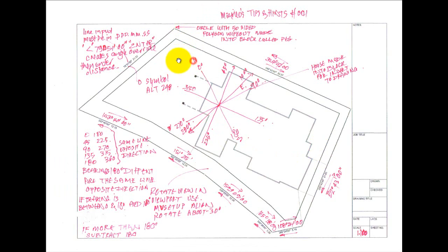Now once you get your boundary bearings and distances in, it's usual to put some sort of symbol at the corner. Now I notice in the plan there they've used a sort of a solid symbol. That's actually the symbol that I traditionally have used as a borehole symbol, and what I traditionally use for a peg is just a circle, a little circle, maybe just slightly wider than the line width, or maybe 2 mils or whatever. I just have a look at it and go with whatever feels right. You don't want it too much bigger.